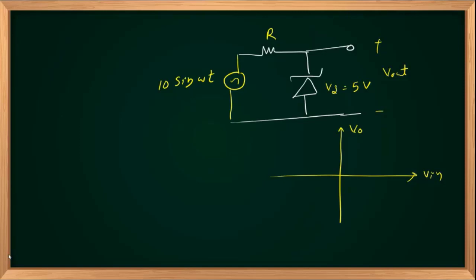So as we discussed, we have 3 different cases for our Zener diode, and we don't know which mode it is operating in. So we will open it. Its anode was connected to the 0 volts reference, and its cathode was connected to this output node. When the diode is open, the right side branch is open. The downward branch is also open because the diode is in open condition. There won't be any current flow through R.